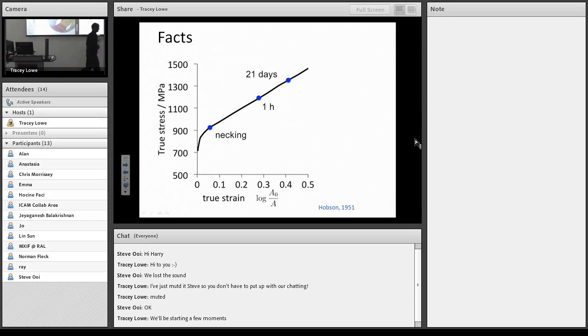One experiment which, as far as I know, hasn't been done is to see whether the effect is reversible if you put a notch in the sample. Because then, supposing you create voids in the stress concentration, they shouldn't go away, because inside the void it should be gaseous hydrogen. But this is something really important to remember, because it helps you to interpret the mechanisms.